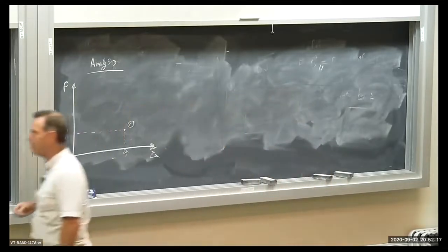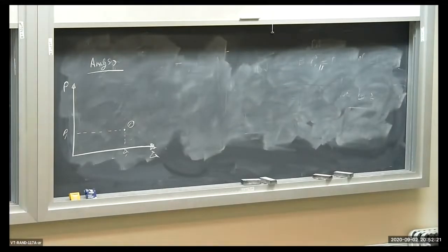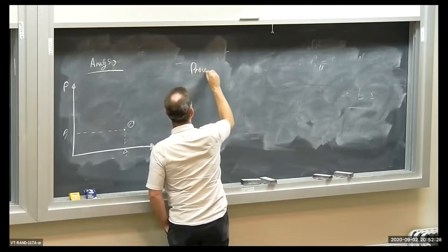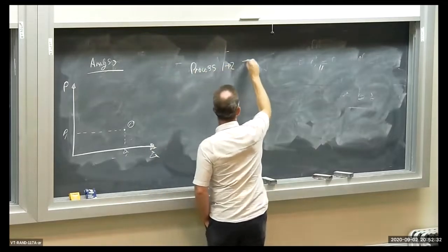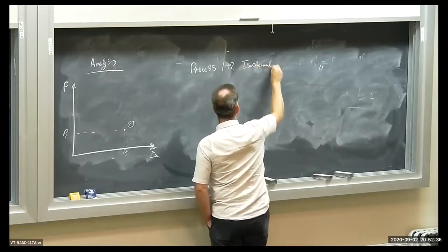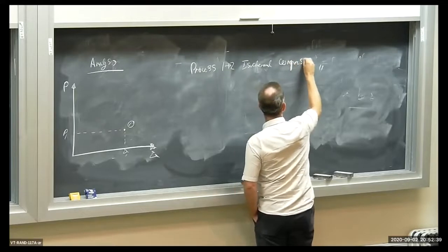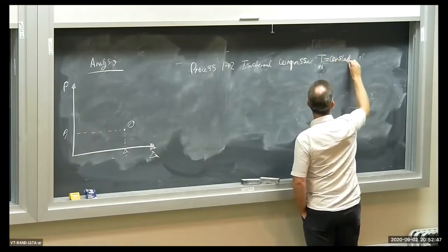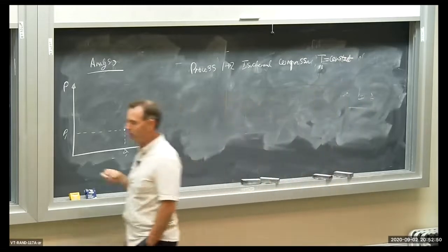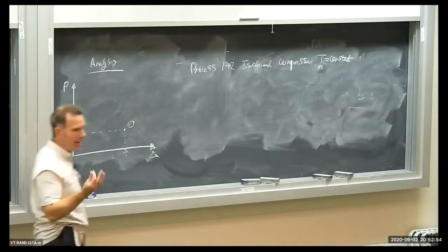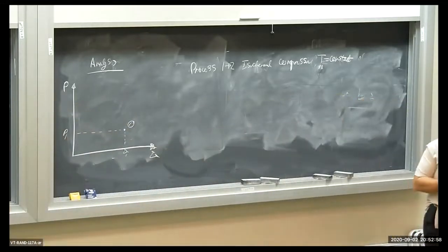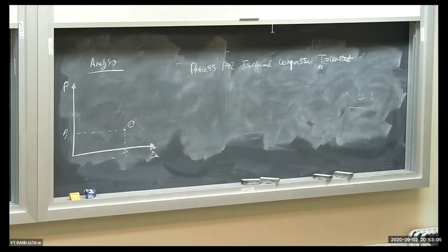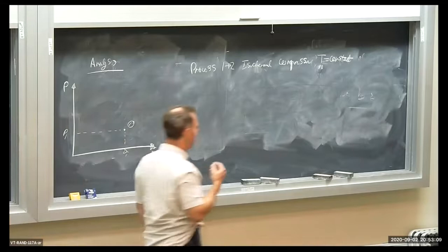So how do I get pressure at state 2? Well, note that process 1 to 2 is isothermal compression. In other words, T is constant. Isothermal means constant or same temperature. Okay, that's good. Now, how can that help me? So the next question to ask is, what quantities or equations involve pressure that maybe we can use? And remember, the ideal gas law is valid. Ideal gas law has pressure in it.